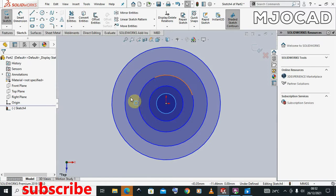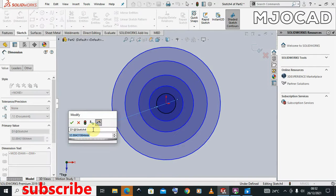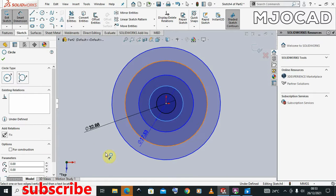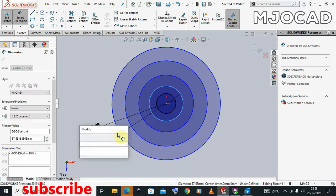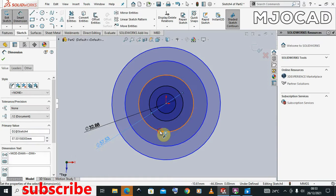And say you have all these many circles that you've done, you can go ahead and give them dimensions. Like I've been telling you, for something that is fully defined, it means that its location is constant. You have given it the dimensions. So for now I'll take what has appeared there, and you're able to realize that they are all becoming dark.